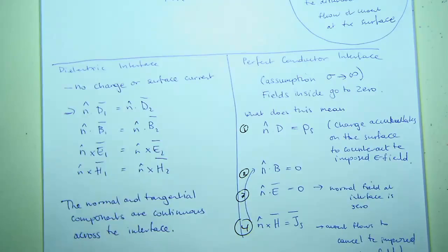If you've got a normal conductor which is ungrounded, after a while, that material won't have enough electrons, or, that's probably not the right way of describing it, it can't suck enough electrons to where it needs to put them in order to cancel out the fields. So that's why you need to ground that box. If that box is not grounded, it ain't going to be a shield, right?